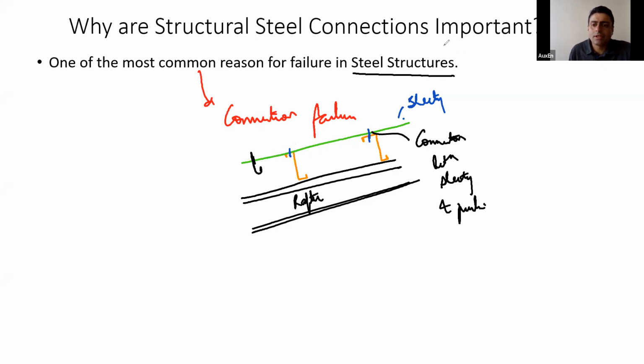So, for example, if you had a purlin like this, then they would provide a J bolt. This is called a J bolt because of its shape. These J bolts were actually a much better option to tie down your sheeting, because they would give you much better resistance.